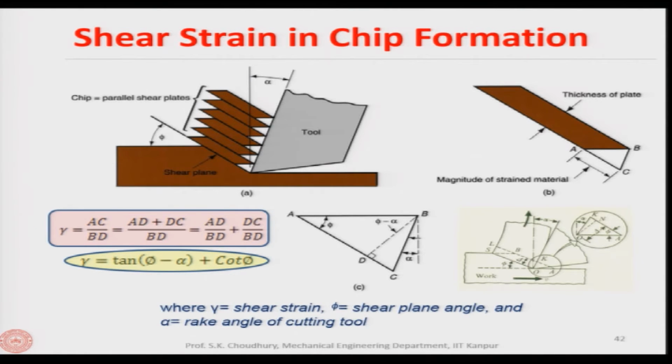As you understand, the shear strain, I have shown it to you earlier, suppose you have a piece of material like that and this has been deformed, for example, like this, by a shear force or the shear stress which is applied. Now, this movement, because of the shear stress applied, is x. I am repeating that, I have already shown it to you earlier, and this is suppose b. So, the strain can be denoted as x divided by b. This is the strain occurring when we have the tau applied, and because of the tau we have a permanent movement of the material, that is a plastic deformation, as x, and the distance between the two layers will be b.